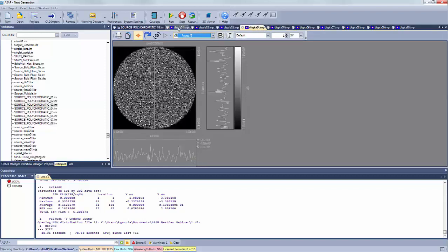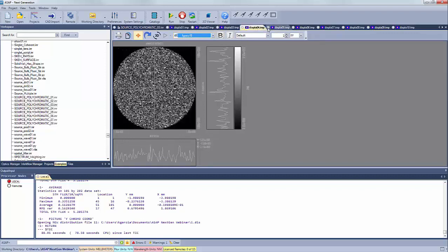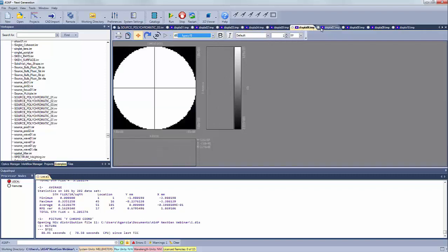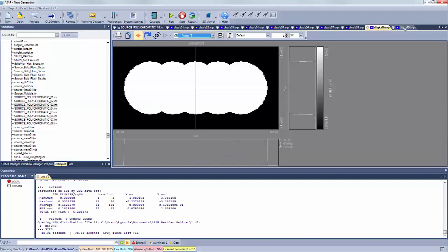This first intensity calculation was done in an angle space, and the second intensity calculation was done in direction cosine space. There are similar calculations for the chromaticity coordinates in those particular spaces as well. This is actually what the LED die set looks like. There are 5 individual dies which are part of this set, and this is a calculation of the luminance pattern of that, and then a corresponding calculation of the colorimetric coordinates of X and Y for that particular source.